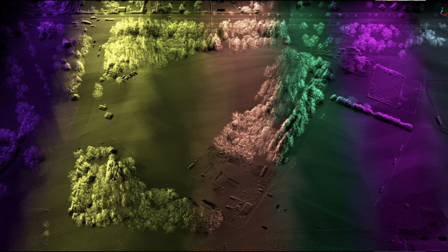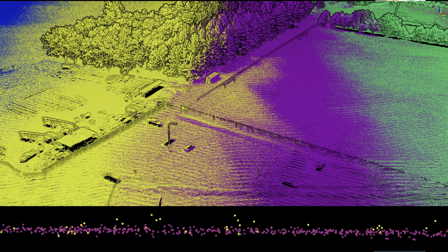But you'll notice that there's areas where swaths may have overlap. So you can see the colors, for example, where purple and green on those woods overlaps. In those areas, we kind of need to be careful with LiDAR. So this is where the LiDAR post-processing kind of begins. And you can see in this graphic here, the purple and then the yellow. And if you look at the profile at the very extremities, or very edge, of that yellow swath, the precision of LiDAR does decrease because it has a much longer distance to travel. And so we don't need that information. We don't need those yellow points. So we can cut them out.